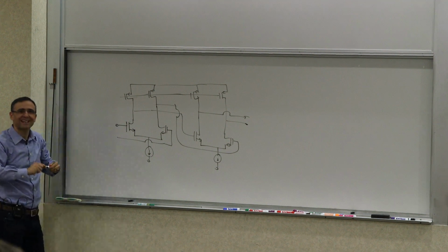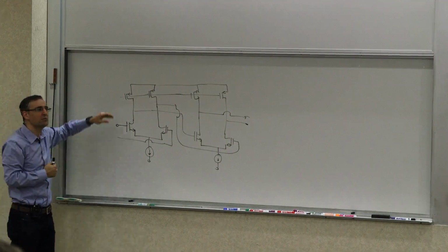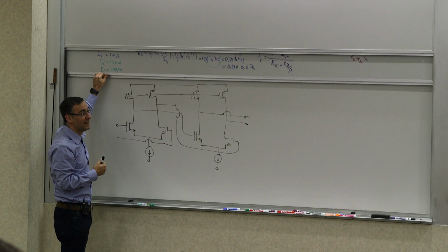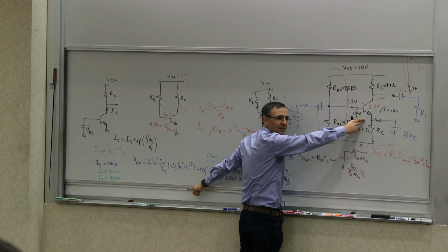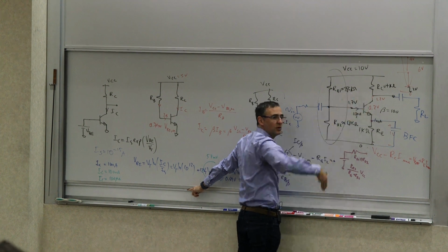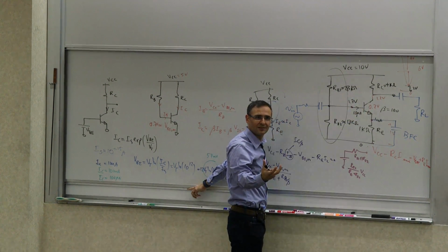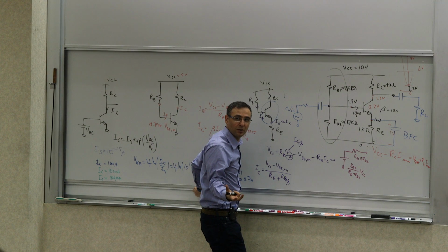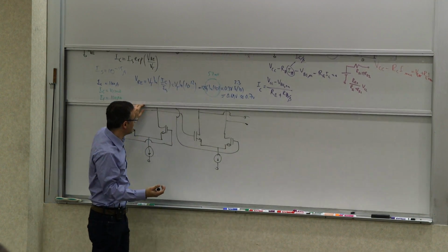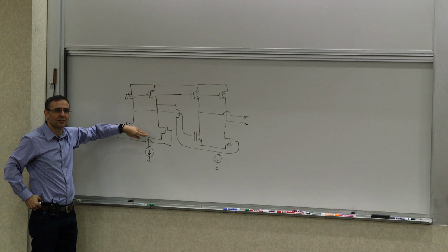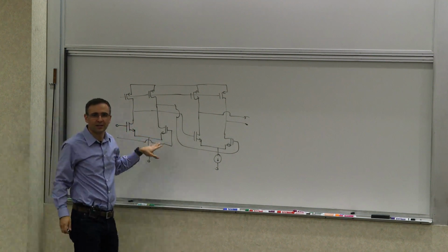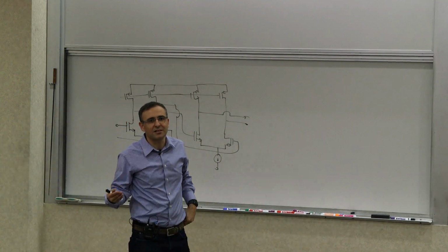So what you may implement like that, which looks very different from this differential amplifier on the surface, is essentially the same thing. These are two very different looking manifestations of common emitter. This is how a common emitter will look in a discrete circuit, and this is an example of a common emitter, or common source, or common terminal 1, in an integrated setting.